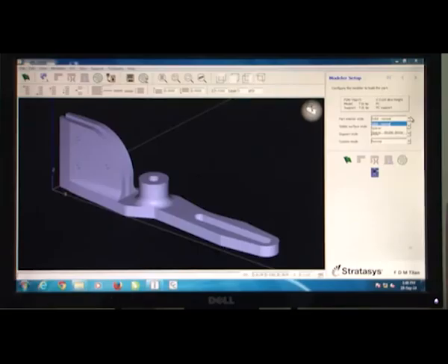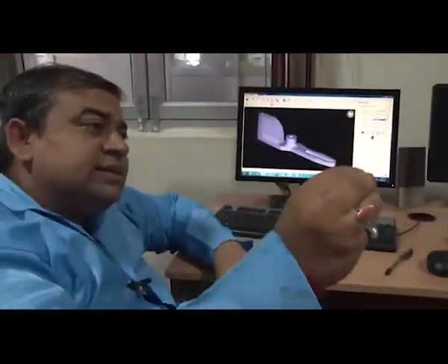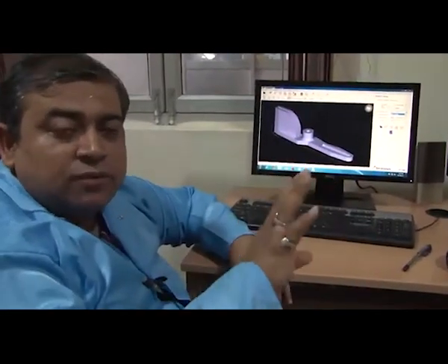So what it means essentially is there are 2 different options this machine has. One is that it has a honeycomb layout structure, which is sort of a lesser density structure, and then there is a flat plate structure. So the tool may move in a honeycomb manner, the tool may also move layer by layer, okay. And the solid normal would mean that we want the bulk to be equally dense, and it may be depositing layer by layer, or even if the tool path is like a honeycomb structure, it would be so close together that it would be considered one whole, okay. So this is the densest form which is available.